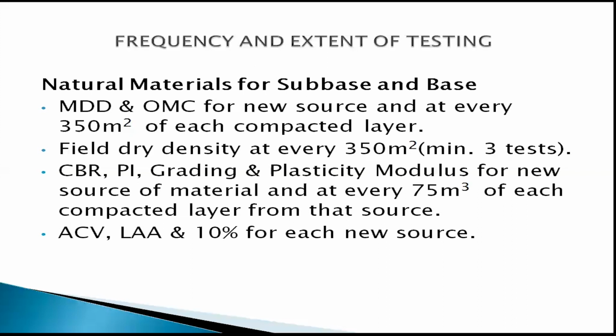Under materials control, once the material is brought to site, the MDD and then the OMC should be determined at every 350 meters squared of each compacted layer. So the MDD and the OMC that we have determined will be used to control the compaction that will be done.